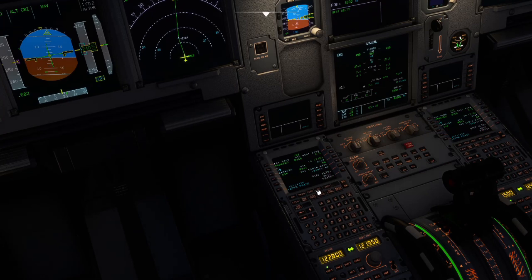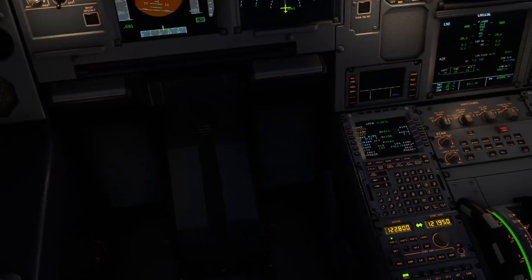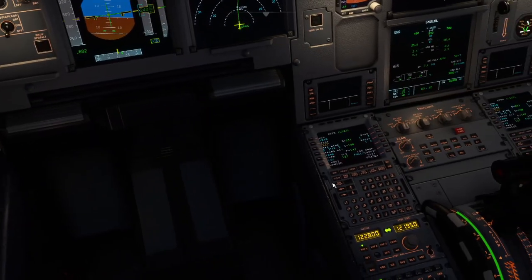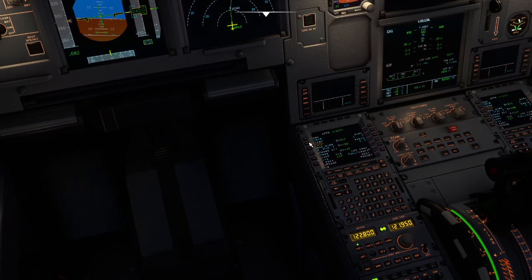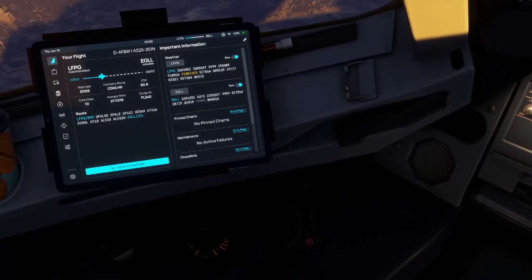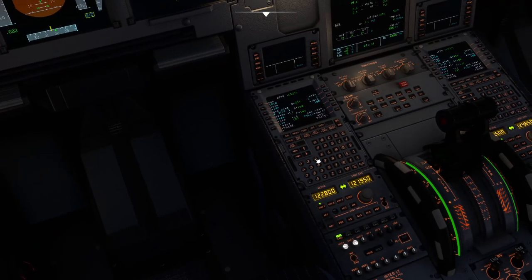The performance for landing, so under the perf page, jump across to our landing data. Runway 27, QNH was 1010. Temperature on the ground, 18 degrees. That is some tropical summer weather. Radar altimeter, decision height, altitude. We'll just go with 100 again. I'm not using plates. It's probably lower than that. Going down to Cat 2. And let's just go to 3010.